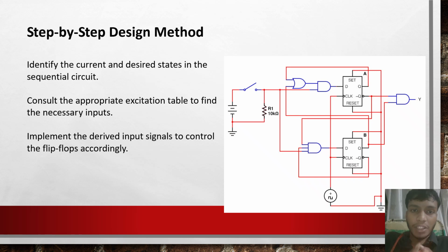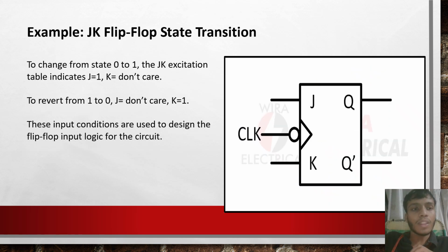Step-by-step design method. Identify the current and desired states in the sequential circuit, consult the appropriate excitation table to find the necessary inputs, and implement the derived input signals to control the flip-flop accordingly.